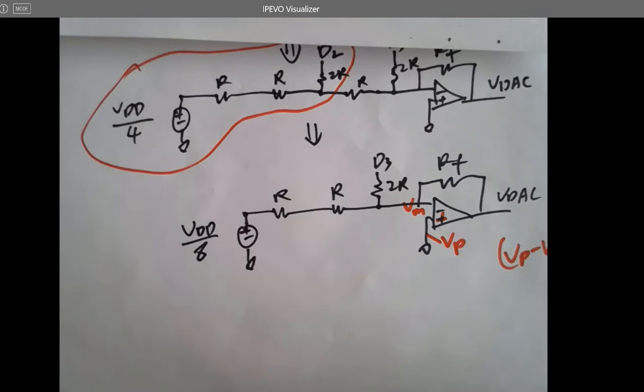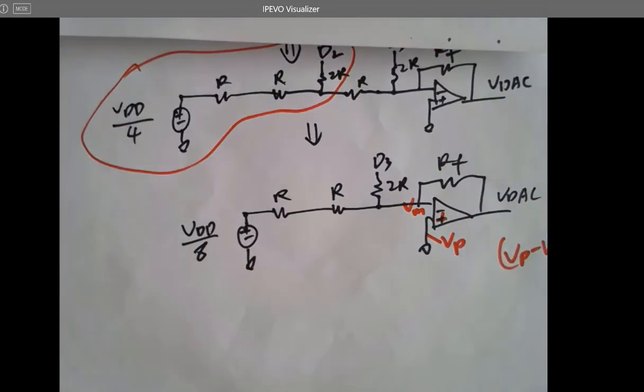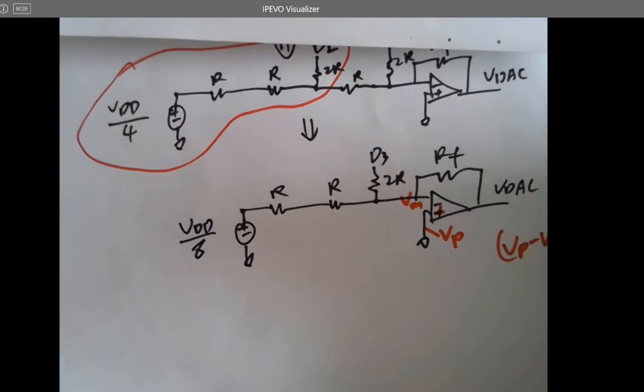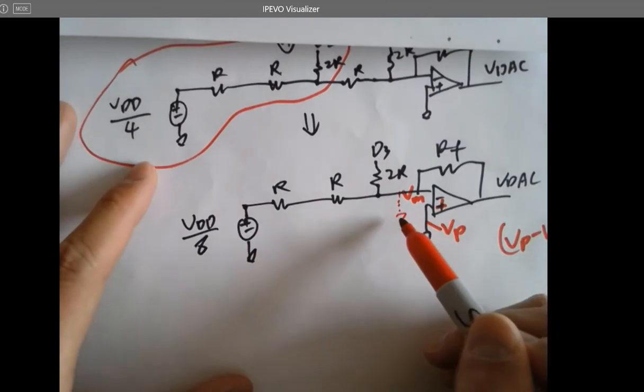If you forgot why, just remember it right now. It takes another week to explain why. Right? So they are virtually equal to each other. That's why you can amplify a signal with a modified gain, not an infinite gain. So if this is grounded, this is virtually grounded as well.